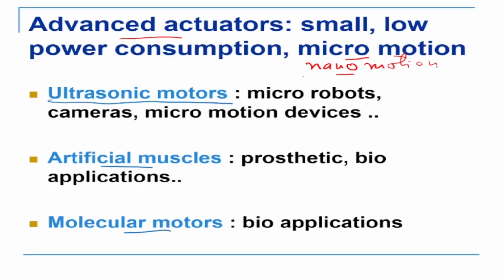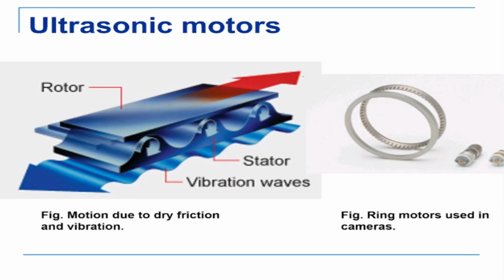Now ultrasonic motors are like this. They work on the ultrasonic frequency principle, and the construction is a little different from DC motors. So this is the rotor and that's the stator. Now the stator is made up of these teeth. Okay. Now this is made up of piezo material.